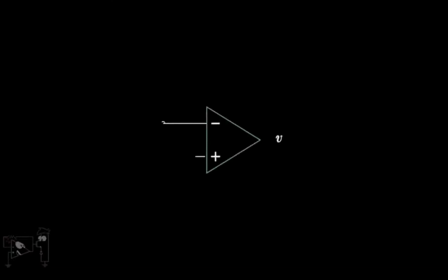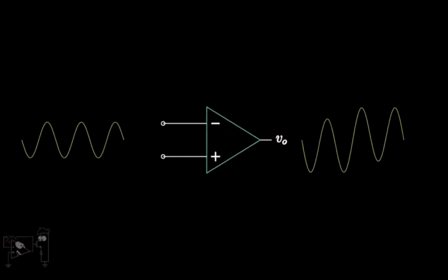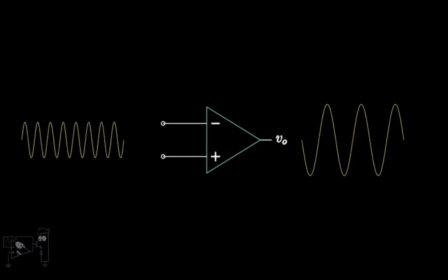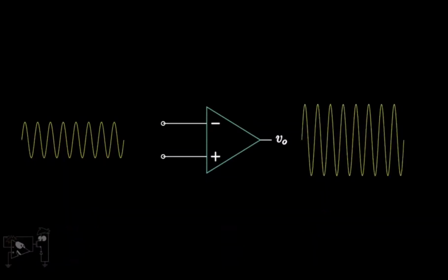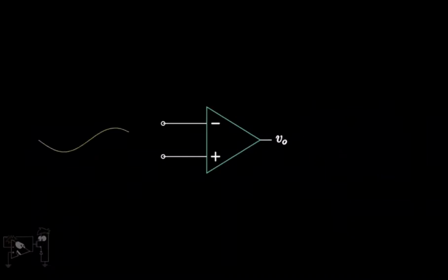In this video, we will see what the gain bandwidth product, one of the figures of merit of an amplifier, is. We'll analyze the frequency response of an op-amp and explore its speed limitations. So far we have not considered frequency as a factor in any of our analysis. That is, we've considered the gain of the op-amp to be constant for any value of signal frequency. In reality, due to the internal capacitances of the op-amp, the value of gain degrades for higher values of frequency.